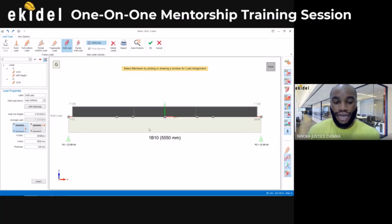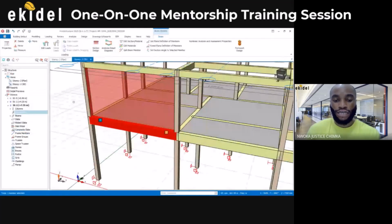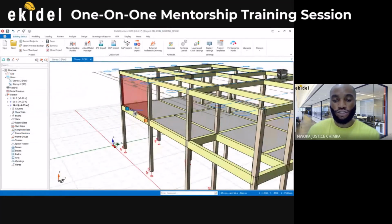Once you have put all this, you then come here and click on this beam. Just click on it. It will add the load to it. I'll click on it now. You can see the load is now added. You can also see the reaction, based on the beam self weight and the load added to it. You then click on OK. You can see that the beam now is not showing the wall load there.